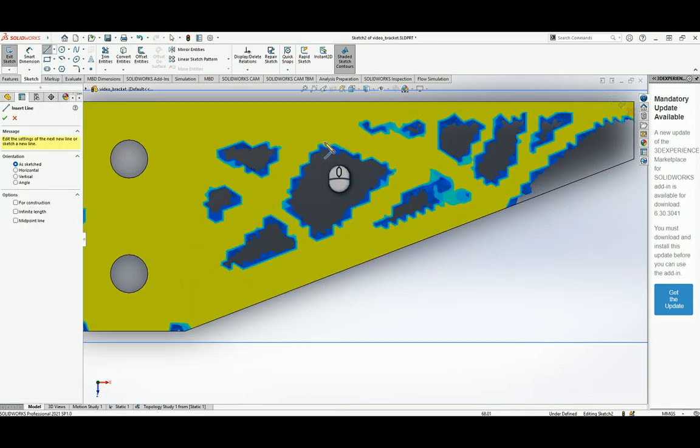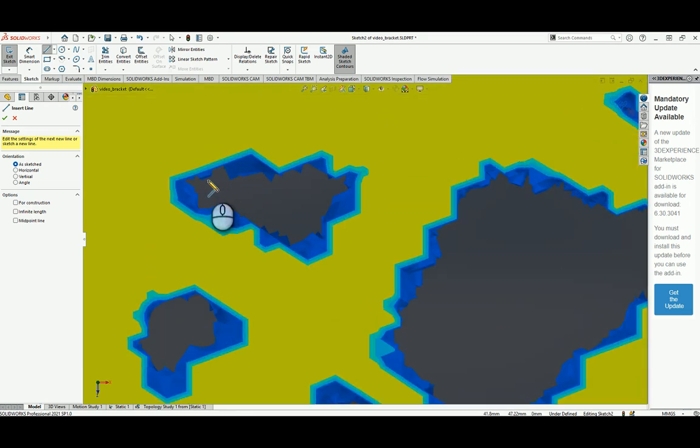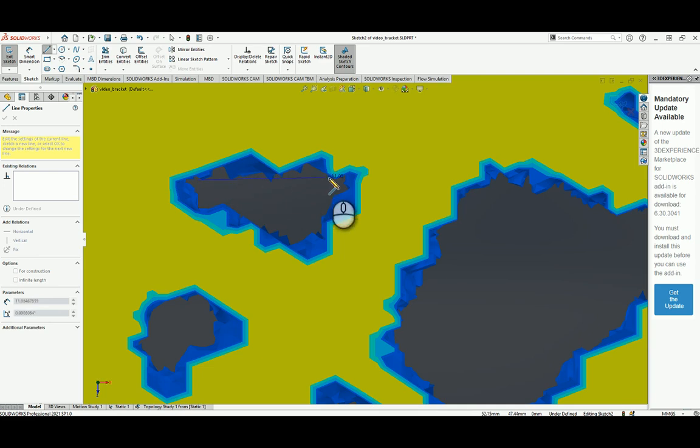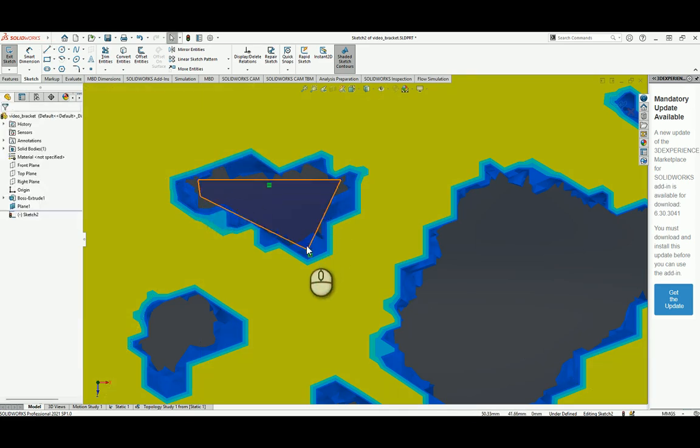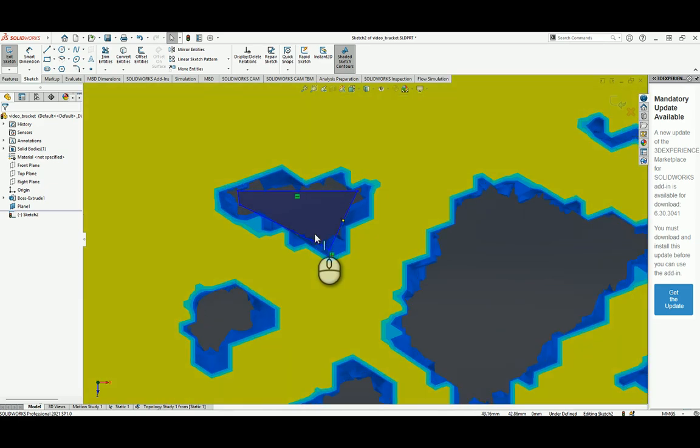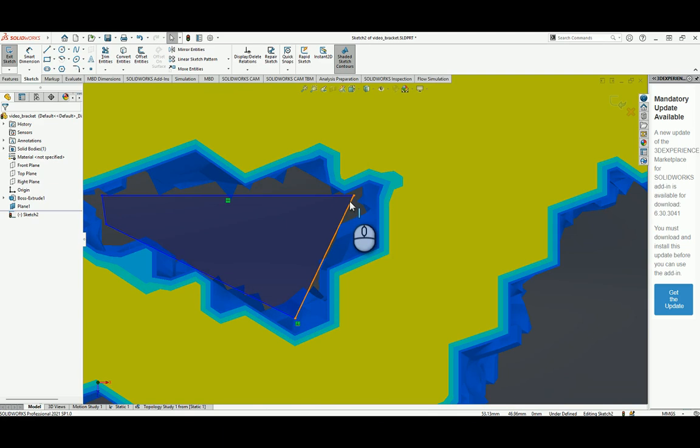Right, so you could grab a line, for example, and we could draw this line here. What we have now created is a profile where we could cut out from the material. Now keep in mind that if we want to machine this part, these vertices must be at a radius that would allow machining. If, let's say, the tool is 5 millimeters in diameter, obviously it cannot go into here, so you end up with a curved edge. So you could specify all those things.